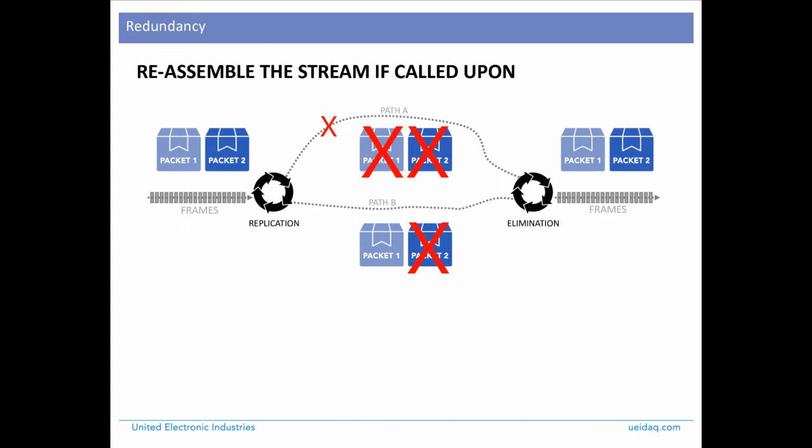Another good test is to act as an end node without the BR profile. What will your device do with that? If you recall, the BR profile adds a sequence number onto time critical packets. Good tests include sending the wrong sequence number on a packet or even on one of the replicated packets.